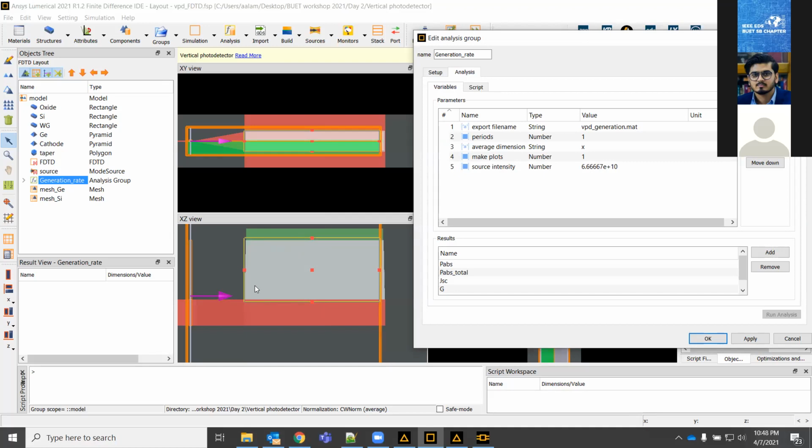You can use a multiple for this period and simulate one slice of your volume, but then extend it by any factor you put here to create a bigger generation rate that you can include in charge simulation.